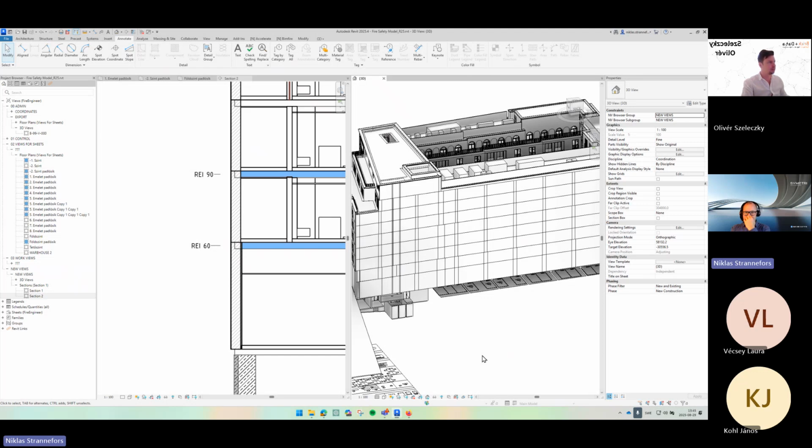The last one, this is going to be a bad example, but we're going to do it because another thing that we need to do is this. Janos and Laura, I'm assuming you as well have this: if there's a roof on a lower deck, for instance, you need to have distance from the facade. Maybe it's different. I know it's 5 meters in Denmark. It's 8 meters in Sweden. It's 10 meters from the facade in Germany. But you have to have the roof fire protected from the facade if it's a lower roof.